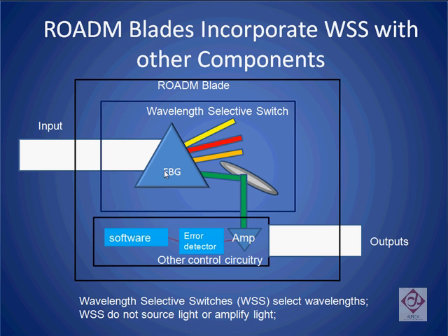In the future, if we want to make these ROADMs more flexible, we may need to make them colorless. That is done by marrying these ROADMs with tunable lasers. Instead of keeping all these frequencies fixed ahead of time, we might be able to reprogram what colors a ROADM works on in real time as the mesh changes. Similarly, today's ROADMs fix the direction of transmission. In the future, we may want to change the direction of transmission from north to south or east to west, depending on failures in the mesh.